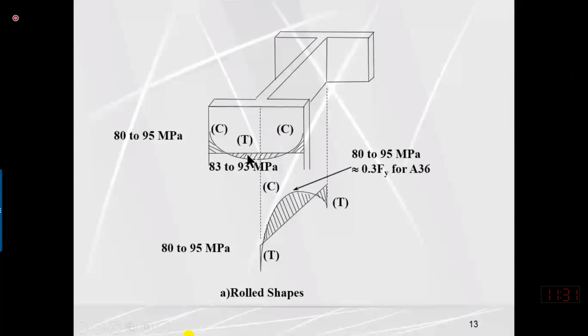And these tensile stresses are approximately, maybe sometimes even equal to yield stress. Similarly, the interior web portion will cool first, and on cooling the web tries to shrink, and the shrinkage of this web pulls the edge junction to the inward side. So the web interior is subjected to compressive stresses, and the ends are subjected to tensile. Tensile stresses do not affect the compressive load carrying capacity.